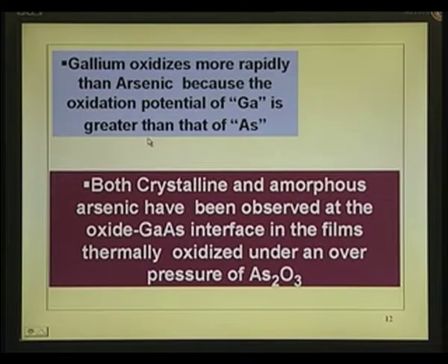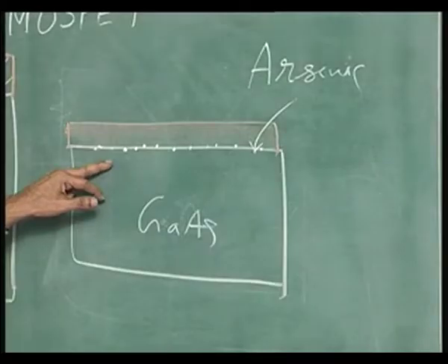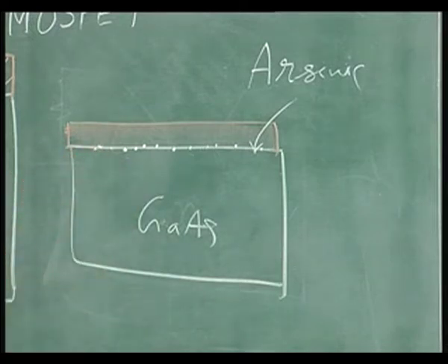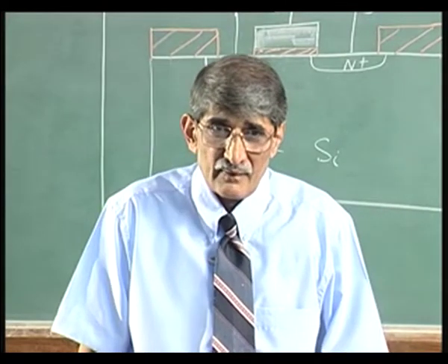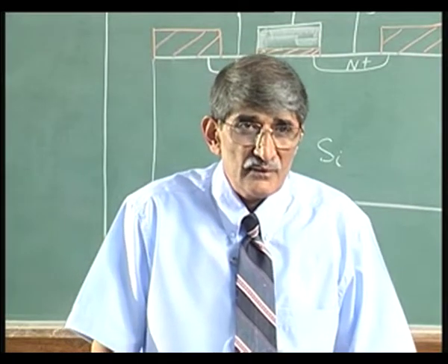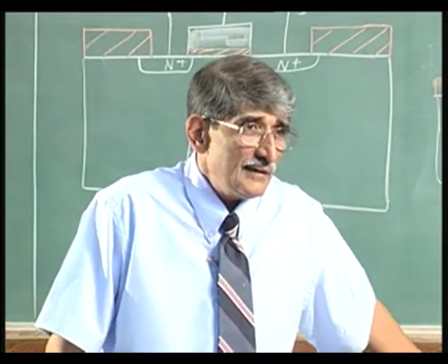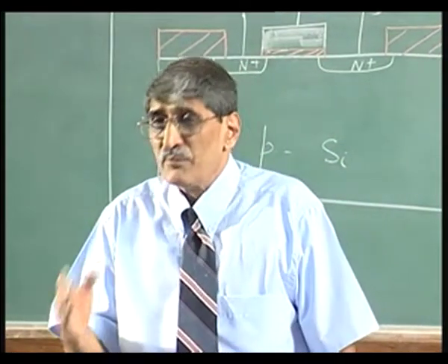Okay. If you have arsenic at the interface, not because it is poisonous for you, it is because it is like putting a metallic layer in between. Okay. Elemental arsenic is there, it is like putting a metal layer there. What will be the result electronically? Levels. Not only loss of periodicity, you have just arsenic sitting there, you will have extra interface state densities. So, high interface state density is observed because of this excess arsenic at the interface. Okay. So, these are the problems which people faced.